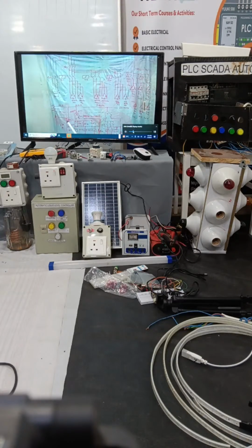Coming to the control circuit, we have our 480 volt system. But since some components are wired onto the door, like push buttons and pilot lights, this 480 volt cannot be used as a control voltage, because by some accidental contact, if somebody comes in contact with any live parts, he will be severely shocked.